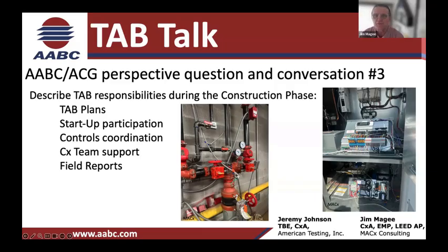On a heat pump system, you're forced to bring in a test stand and actually flush the system and flush the field and then put them together. A normal hydronic system, you don't do that. It's almost like you get a better install when you're doing a heat pump system because there's a geothermal field involved.